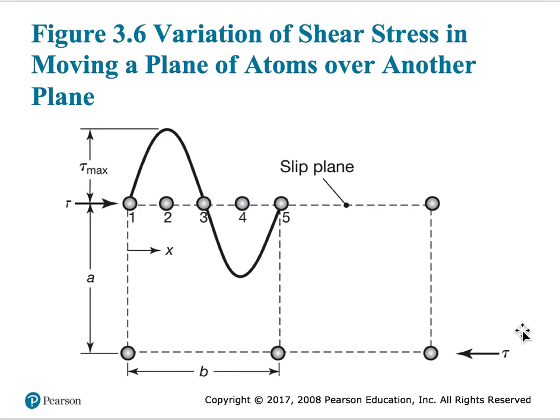As I said to you, the movement of atoms can happen much more easily if you push the atoms in such a way that you are creating a wrinkle in that plane. The movement of those atoms happens more easily along the plane with the maximum number of atoms, which is called the slip plane, and each material has certain planes on which this can happen most easily.